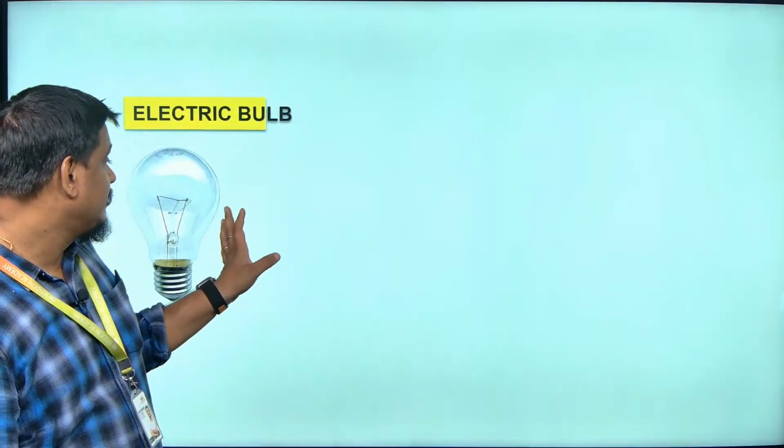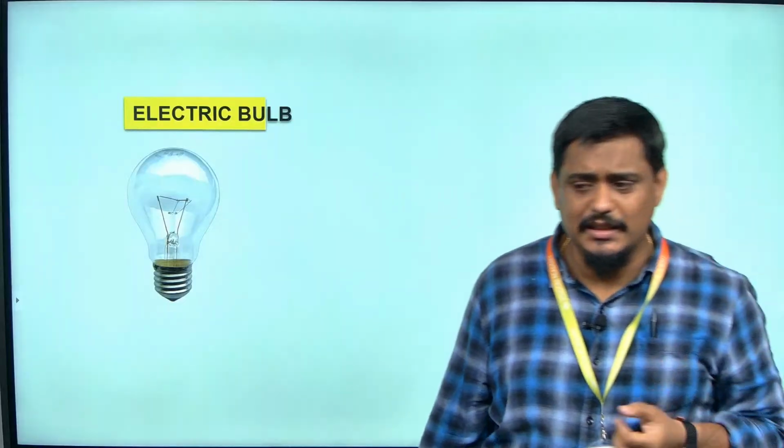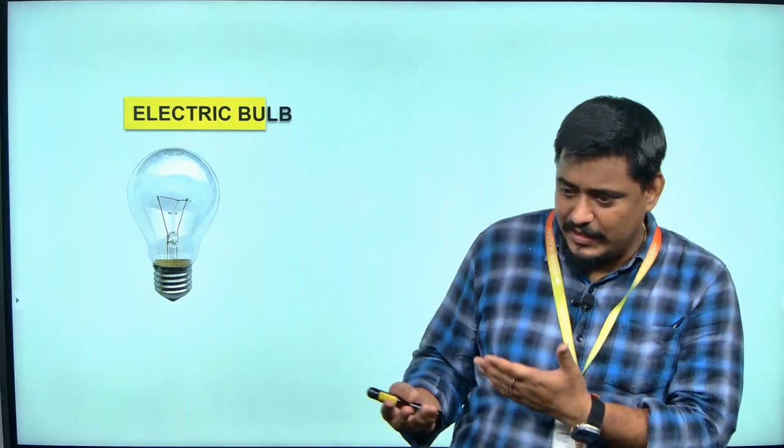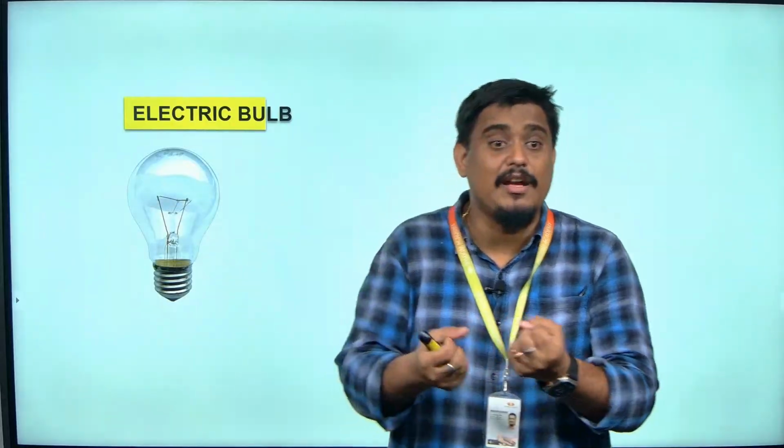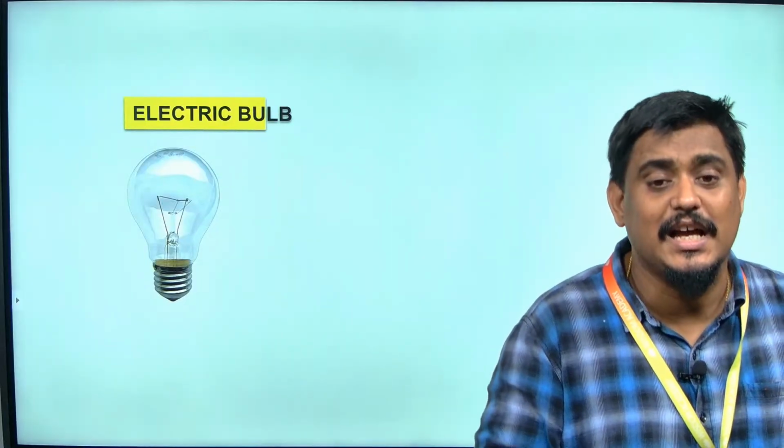This bulb is working on which phenomenon? Heating effect of electricity. You know how this bulb works? Inside the bulb we have a tungsten wire. You may ask, why tungsten? Why not copper wire? Good. We want something to have a high melting point. Why is it so? Because heat will be produced. If it melts, the circuit will break, then the bulb will not glow. It glows on heating, so it should have a high melting point. That's why we choose tungsten as the material, because tungsten has a high melting point.